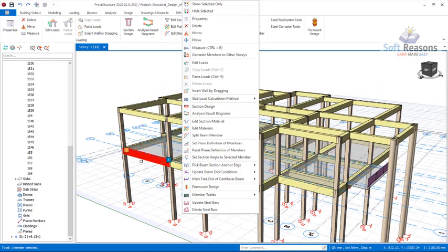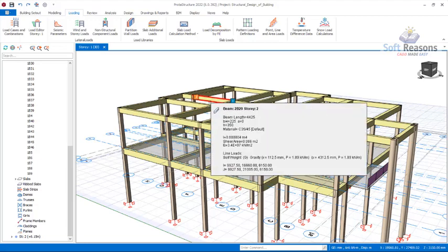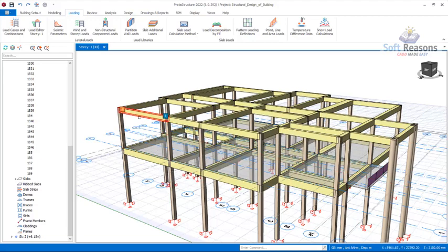All right, so you can apply that by being on the first floor, moving the grid line just where we are now at the first floor and not the roof level, because we wouldn't apply loads to the roof. It's going to be minimal, okay, for the roofing structure.